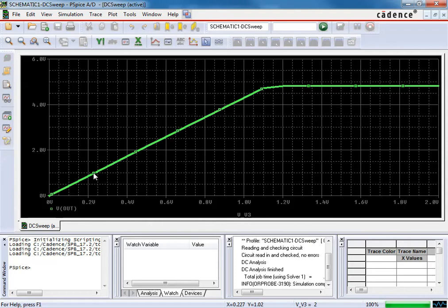And you can also see at the bottom of my screen there's an X and Y, and it's actually telling you what the X and Y values are where your cursor is. Now we should also notice here as we go up, we're saturating. And this is a property of op amps that we absolutely know about. If we remember back from circuits 1, if we had an input of 1.4 volts, a gain of 4.3, that's going to be above the power supply of 5 volts.